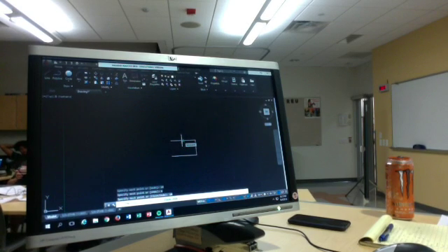So, like I said, we're out in arbitrary space. We want to close this thing, but as J.C. Malitsky, one of my other foreman teachers, put it, we're really lazy. When I was getting my associates, their motto was be efficient. Just really lazy. So you type C, enter, and it closes it. So there's your rectangular box.